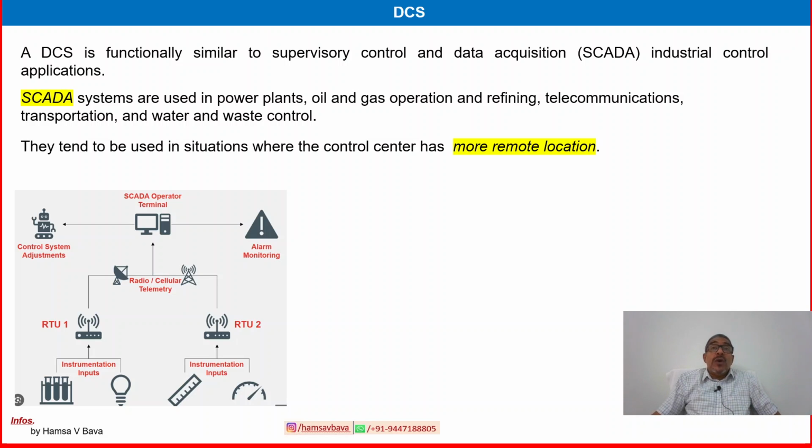In a refinery or a gas treatment plant, it's only one plant or two or three plants that you can configure or interconnect. In that case, DCS is best, but if plants are scattered over kilometers, or distributed or remotely located, then SCADA will be more suitable.